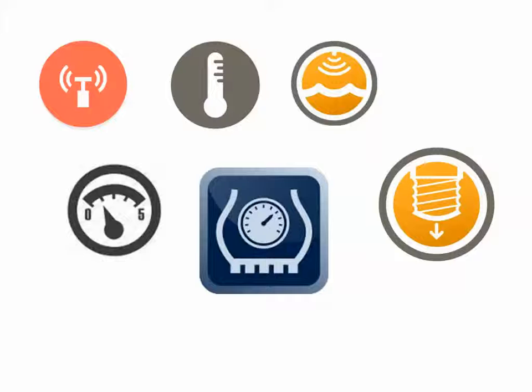In this class we will talk about different types of sensors. The type 1 sensor is known as a digital sensor, which will give the output in digital format. The next one is the analog sensor, which will give the value in analog format. Most microcontrollers will be able to support it, or you can use ADC, analog to digital converters. If you talk about analog sensors, the Arduino board has 6 analog pins. Similarly, for digital, we have 14 pins in the Arduino board.